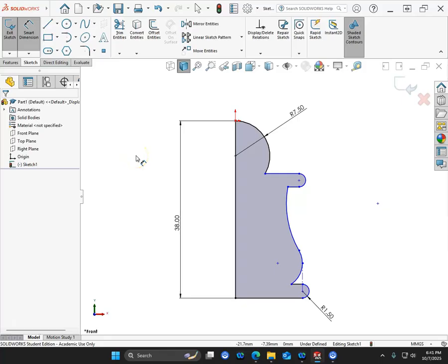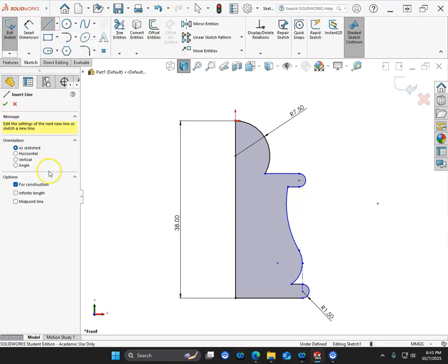So since this isn't a center line, I'm going to have to divide it. So this leans back to anything that has symmetry, mirrors. I really want to just put in that center line, and since I didn't do it first, I'm going to go ahead and do it now because I want to utilize those diametral dimensions. All right, so vertical infinite length.